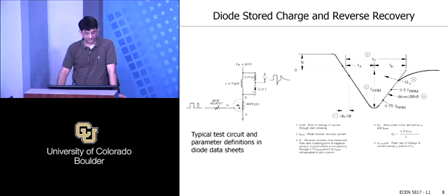So the inductor current is going through this diode, and at the same time you turn on this device, and so you're going to see that reverse recovery through this diode. Essentially it's the same circuit, just backwards. The diode is above and the MOSFET is below, but nothing else is different. So what you will see is that this was the current through the diode in the beginning, and then the current will decrease because the current is now being picked up by the MOSFET.